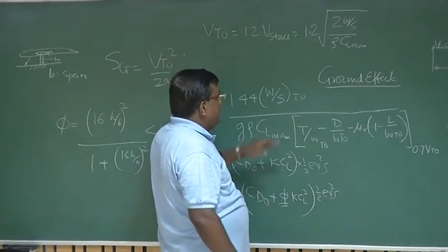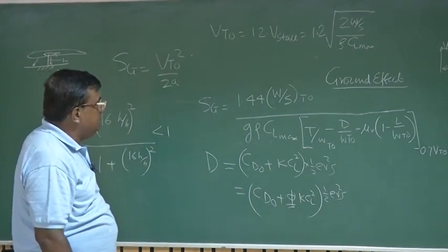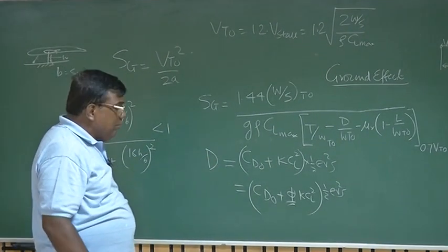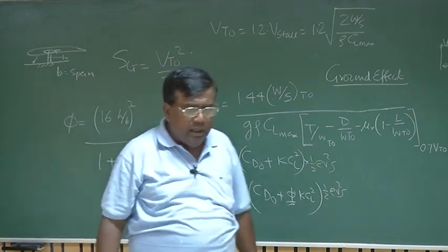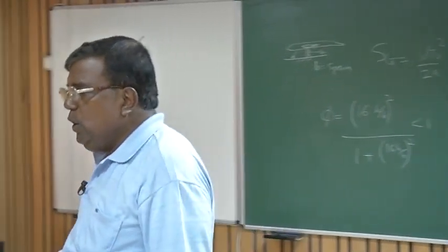So coming back here again, once I know this, how to calculate, and sometimes you will find in much literature, there is an advice. When you're calculating the lift, don't take the CL max, you take 0.8 times the CL max. Okay?